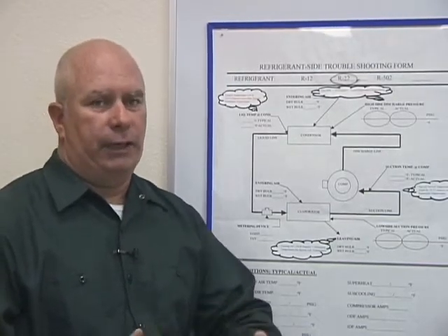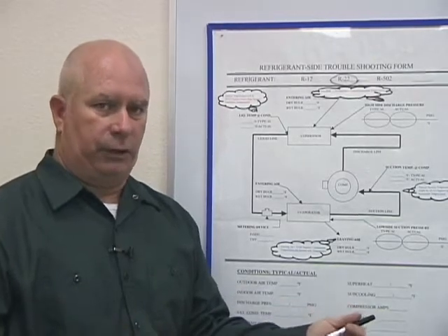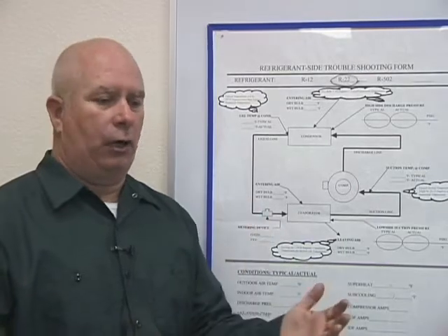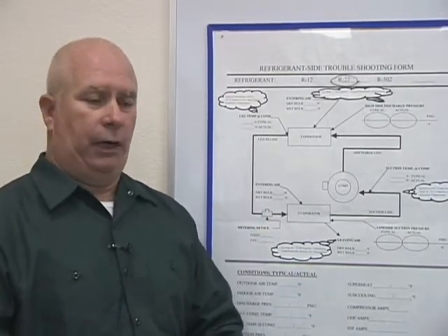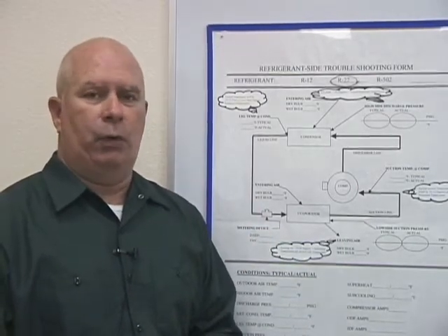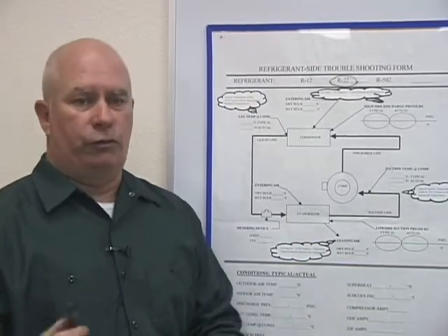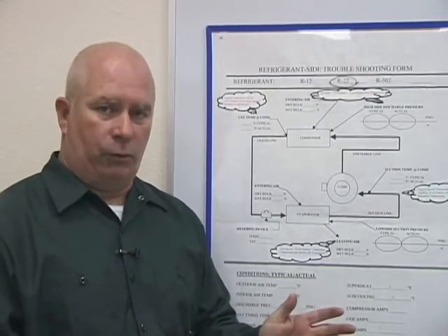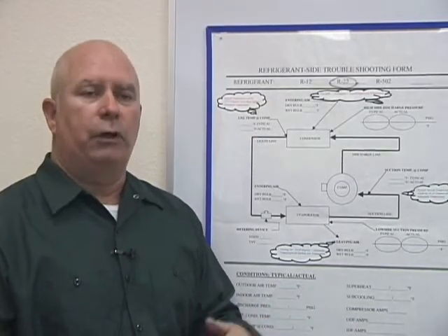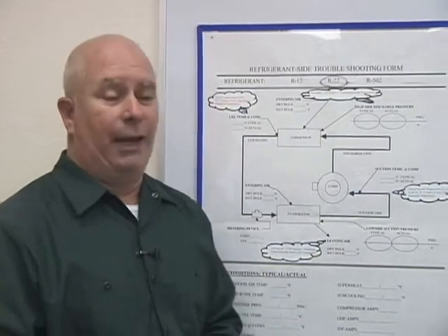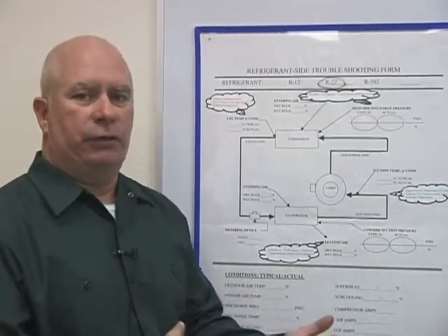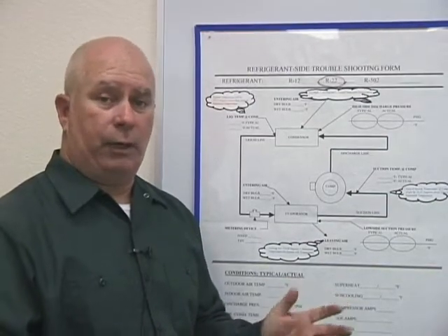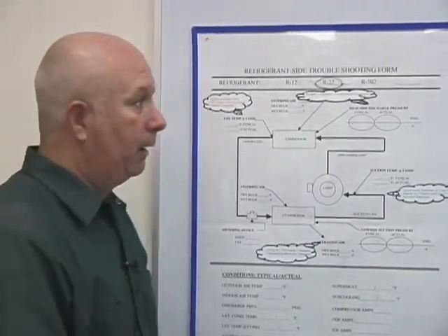Now, 410A is also going to be called different things by different companies. So you cannot just sit there and think R22, 410A, everything's happy. That's not going to be the way it's going to be. Suva, DuPont, all make their own brands on this. They should be called 410A or R22, but they may have their own nomenclature. And remember, it also deals with how you work with that refrigerant. Some cans are upright, other cans are upside down.